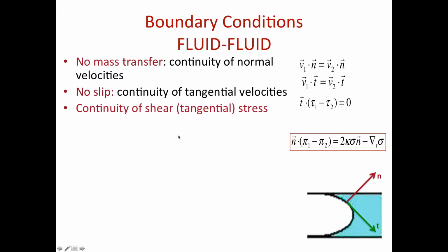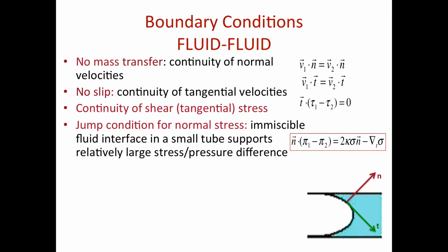And we will also assume continuity of shear stress. So for the most part, everything is continuous across the boundary. I could have different velocity profiles in different fluids, but they have to match on that boundary, and also not just velocities, but their derivatives, because shear stress depends on derivatives times the viscosity, they have to match as well. Okay. So I know that shear stress is some combination of coefficients times derivatives of my velocity. Okay.